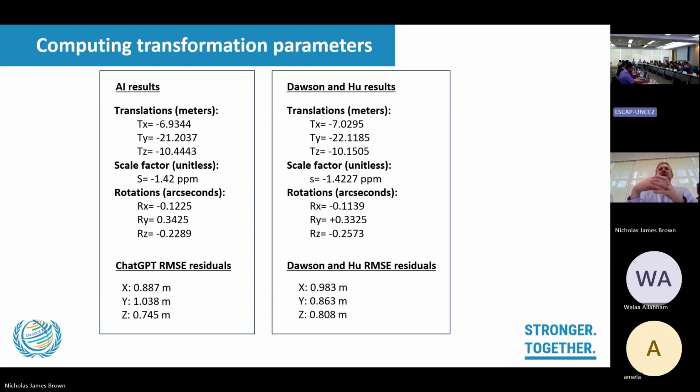point that you have. But if you're talking about moving from a historical datum on an old spheroid, I think that baseline length is probably going to be the least of your error sources. I think the bigger impact of the error sources is going to come from the uncertainty of the original coordinates, and in particular the height. That's probably where your biggest error source is going to be from. That's what's causing the biggest residuals here. It's nothing to do with your new data set. It's more got to do with the quality of your old data set.